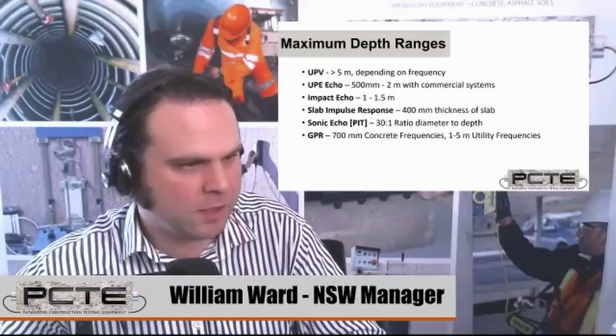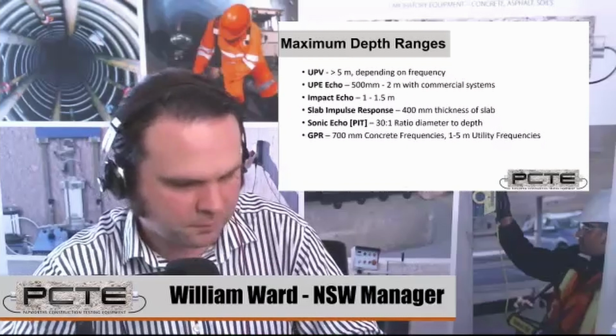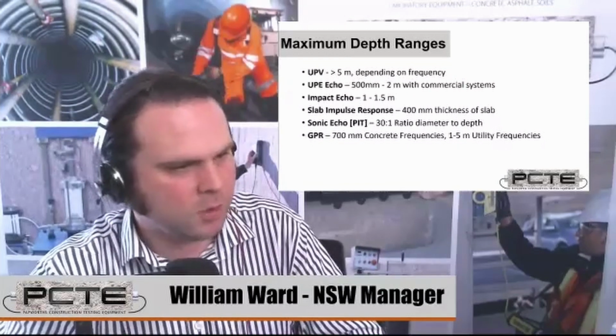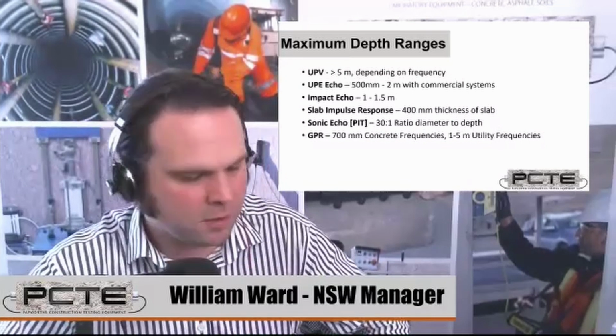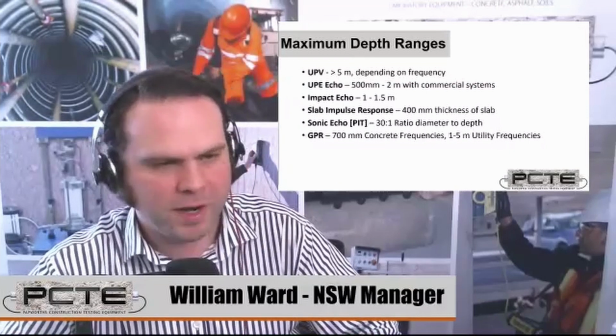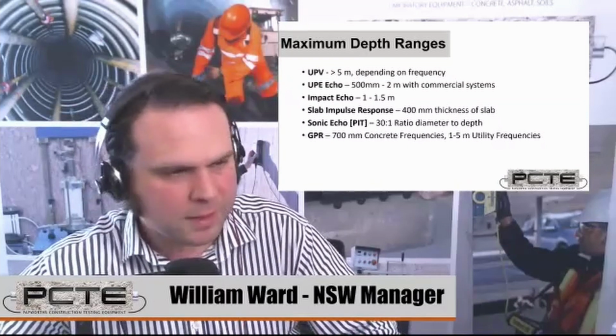The impact echo technique is appropriate down to 1 to 1.5 meters for thickness determination and voiding close to the surface. You'll find it's more difficult to find voids directly at the bottom of a thick structure, though that's less of a problem for normal slab thicknesses, 100 to 300 millimeters or so.